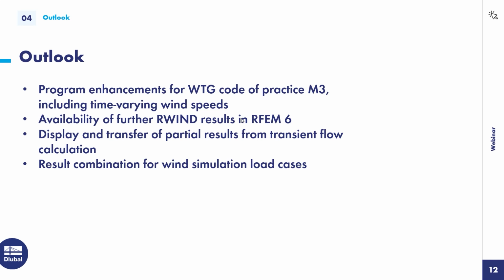And last but not least, we want to implement result combinations for several wind simulation load cases. So if you have calculated multiple wind directions and have several load cases, and you just want to know what are the biggest pressures and biggest suction loads, then you can create a result combination for those load cases, especially for these wind simulation load cases.